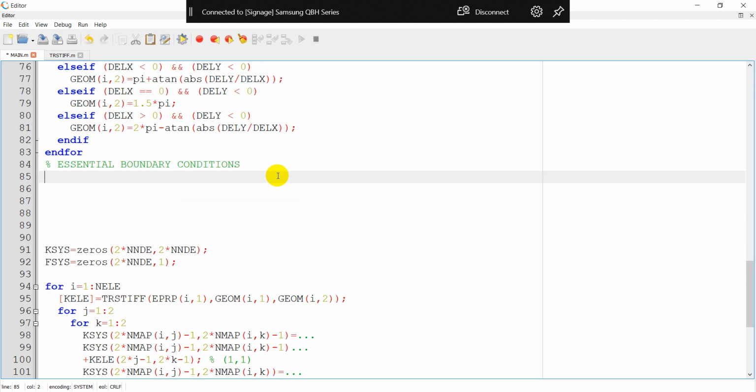Well, that's up to you. I mean, how to set up the architecture for the number of boundary conditions. I think I'm gonna use the Lagrange multiplier, so that's gonna make your matrix bigger. The point is that if I use Lagrange multiplier, I have a freedom. I can do it, not only just fix it as a boundary condition. We can apply the displacement if we want.